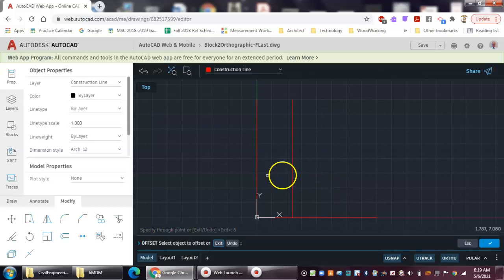I have to allow space between those views. So I'm going to click on this line, and I'm going to move that over. The space I'm going to allow here is 1 inch. I hit enter. Now my depth is going to be boxed in over here, and my depth is 1.5 on that part. So there we go. So there's 5 out of my 9 lines.